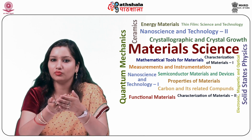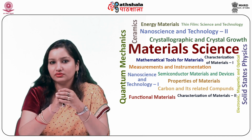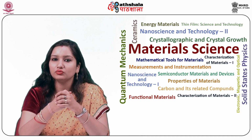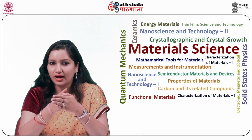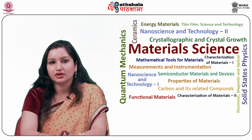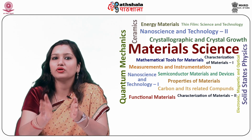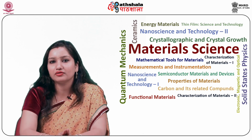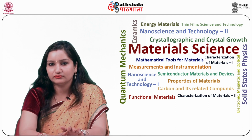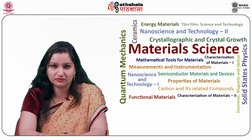Bulk ferroelectric photovoltaic effect is a fascinating phenomenon with many unique features, such as extremely large photovoltage, where the photocurrent is proportional to the polarization magnitude, and charge carrier separation in homogeneous media. In the bulk photovoltaic effect, the remnant polarization and the polarization-induced internal electric field exist over the whole bulk region of the ferroelectric, rather than a thin interfacial depletion layer as in the case of semiconductors.